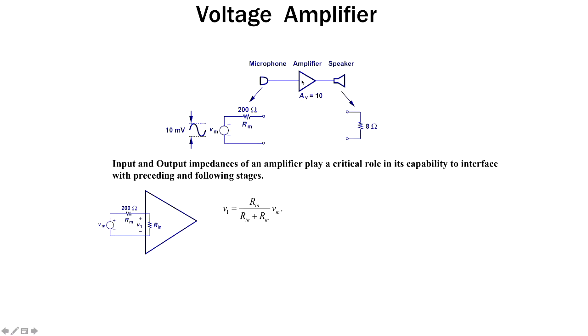That is the reason in an operational amplifier, when you check, the input impedance is a very big value. They will provide it. This is our input impedance, a big value, so that you are not losing any signal when you connect your operational amplifier. I am also talking about a transistor based amplifier. For that also it is very important that the input impedance should be very high.